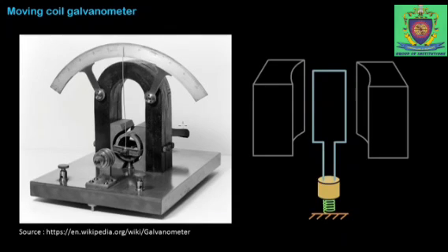Now considering this particular diagram, if I know the resistance and the current, I can find the voltage. And if I know the voltage and current, I can find the resistance. Where is the resistance? Here is your resistance. One coil will be there. In that coil, if I identify the resistance and know the current, then I can identify the voltage also. Then is it acting like a voltmeter also? Obviously yes, it is acting like a voltmeter also. Here it will measure a very small voltage, okay.